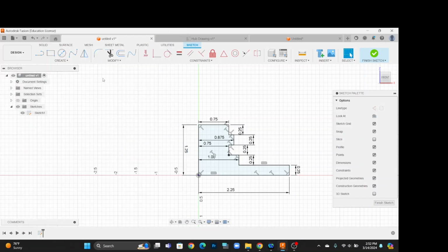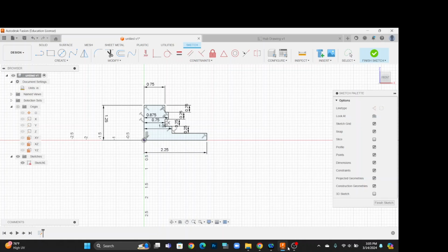So let's look here, and that's our z-axis. If I click on this triangle next to the origin, I can see my z-axis. As I go over it, that's my z-axis, and that is the line of symmetry. The sketch is fully constrained and it is tied to the origin here. It is a closed shape. So I'm now ready to revolve.